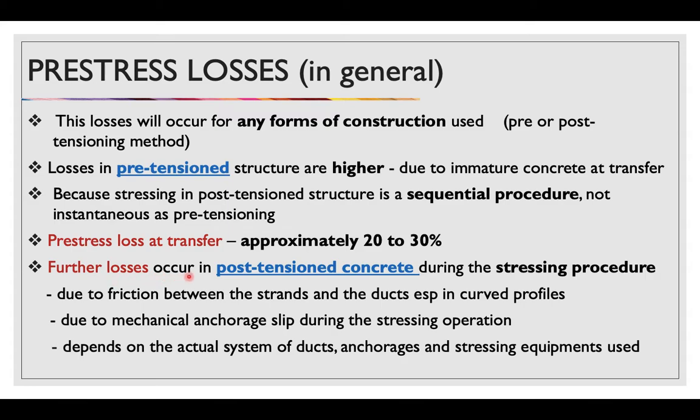Further losses occurring in post-tension concrete during the stressing procedure are due to friction between the strands and the ducts, especially in curved profiles. So this is for post-tension concrete structures.